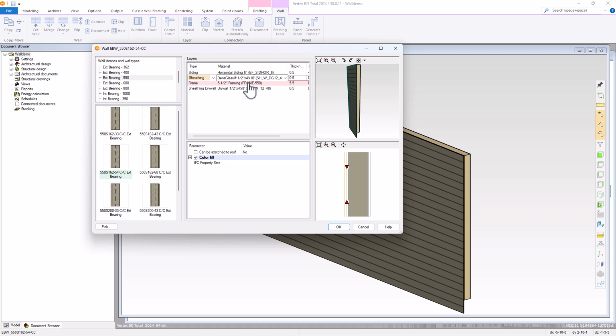Some wall layers have the framing tools associated with them, such as a frame layer. Framing tools are rules that control how materials are handled for the specific wall layer. Examples of some of the settings can be stud spacing, specifying different framing materials for different parts of the wall, and setting specific framing details.